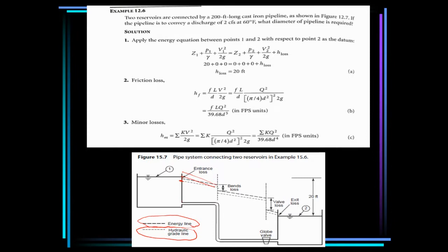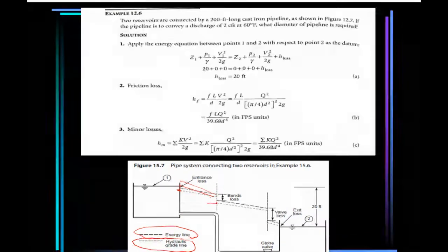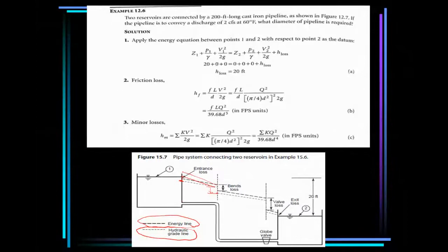Here there is a bend, a 90 degree bend. There is also another loss, and that is why you can see at this point the pressure head goes down, from here to here. There is loss of pressure head due to the minor loss as a result of the 90-degree bend. As a result, the velocity head or the energy grid line will also go down.